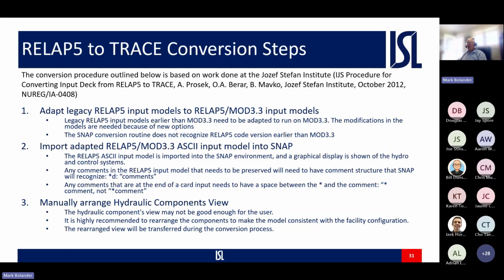And then once you import your RELAP5 model, you're going to want to rearrange your components because SNAP doesn't know what your model looks like, so they'll be in disarray. So you want to take the time to rearrange your components so that it looks familiar to you and to others that are going to be using your model.